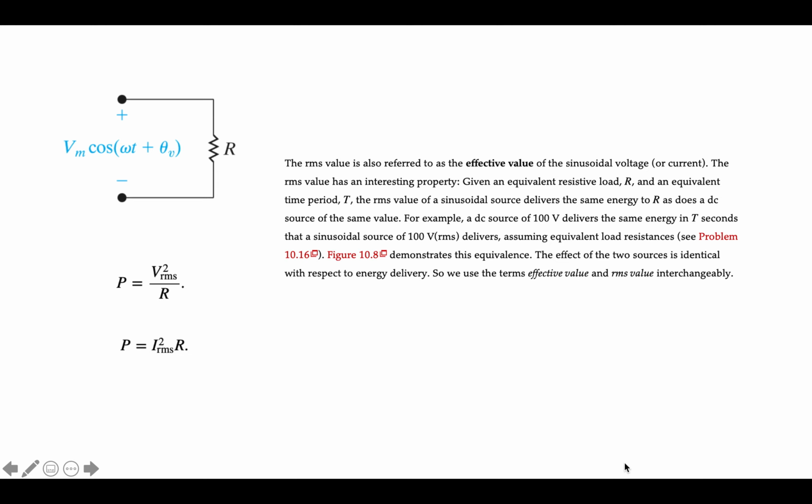So, for example, when you're told that your household runs on 120 volts or 110 volts, that is actually the RMS voltage. And if you were to hook up your power from your home to an oscilloscope and actually track a peak-to-peak waveform, you would not get 110. You would get 110 times the square root of 2. So RMS is commonly used in AC power discussions in courses that follow on past circuits.